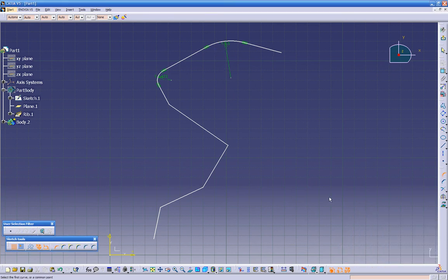1.5. Or we can highlight the whole area. And I got all the points highlighted if you see them. So right now, if I give it a dimension over here, that's gonna change all of them. So let's put ½ inch. And all of them it's ½ inch.